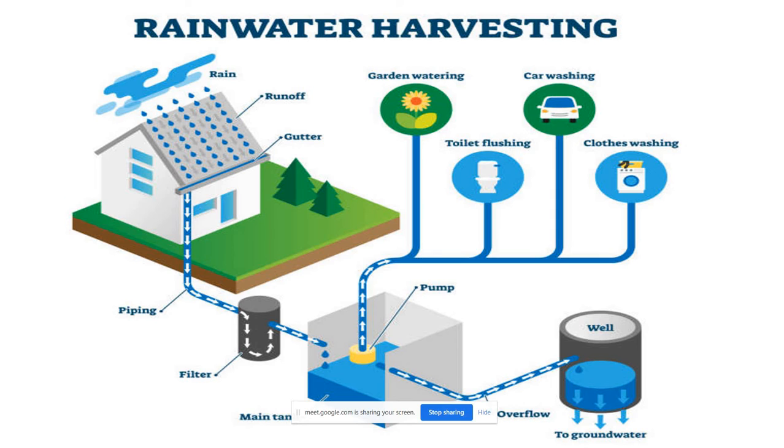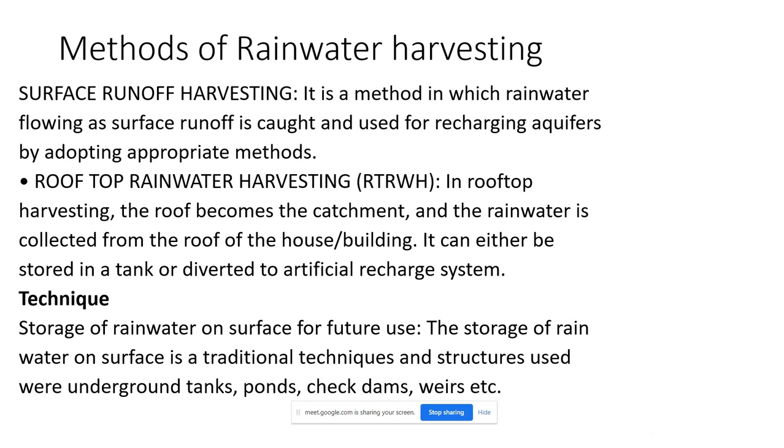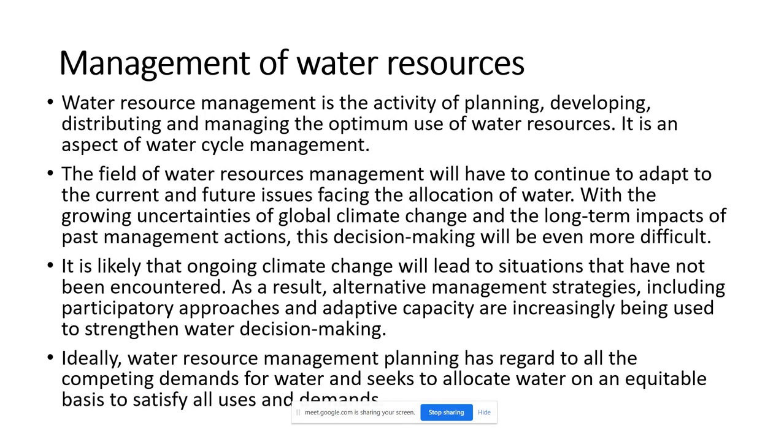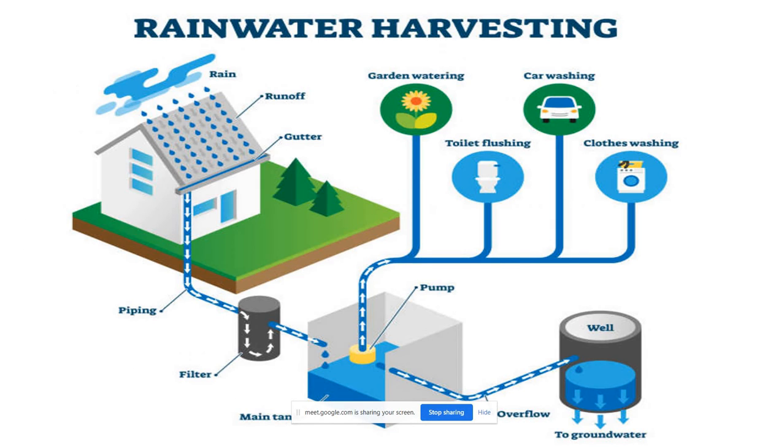In situ water harvesting is a special type of water harvesting in which the rain incident on a plot of land is harvested there itself by storing it in a pit or trench. This method is useful in areas having heavy rainfall with quick runoff and no aquifers to recharge the rainwater. In such a situation there is no need of the traditional approach of collecting from a donor catchment and storing in a recipient area.